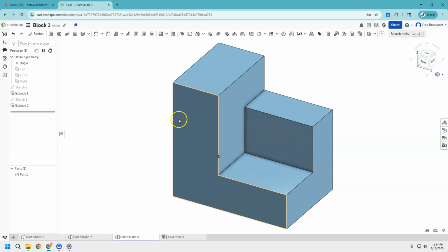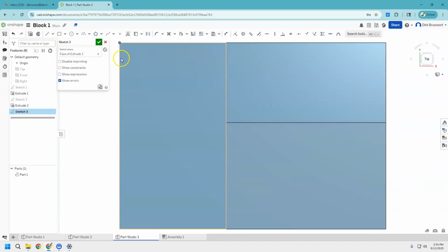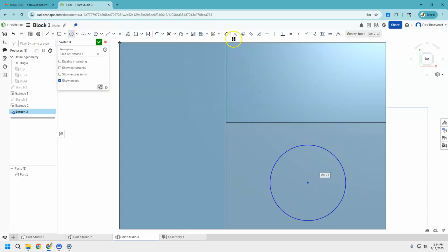So we've done adding on to an existing thing. Now we're going to talk about removing. So we're going to add the circle. The circle goes right here. I'm going to hit sketch. Click on that spot. This kind of becomes a repetition. Grab the circle tool. I'm just going to draw a circle. Doesn't really matter the size too much. I'm not going to select on any highlight points. That's also important. I'm going to click in dimension.